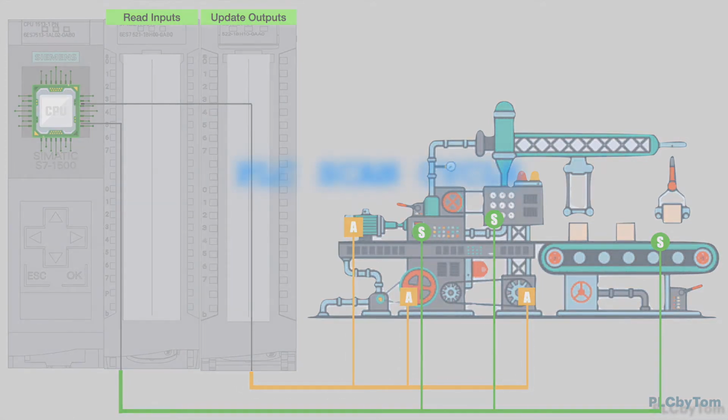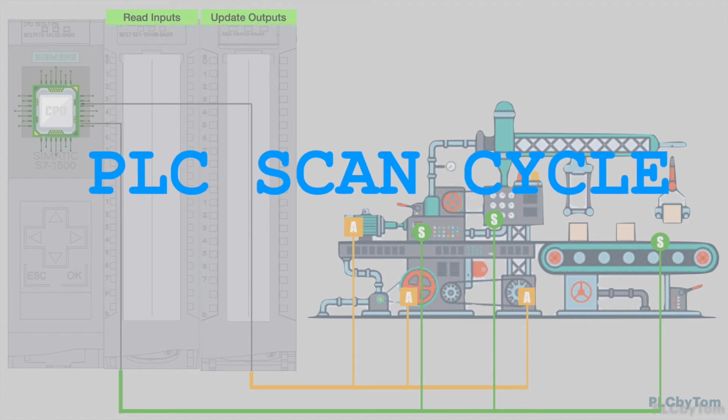All this is one PLC scan cycle. After one PLC scan cycle is finished, the new one starts. Duration of a PLC scan can vary and will not always be the same. Typical PLC scan cycle takes around a millisecond, depending on capability of CPU and user program load.